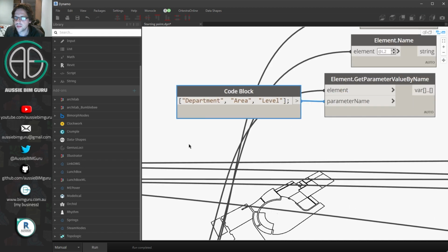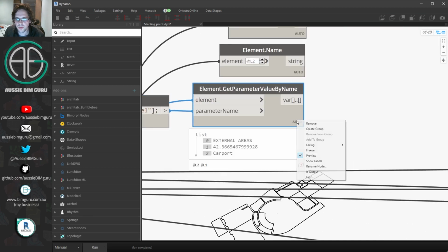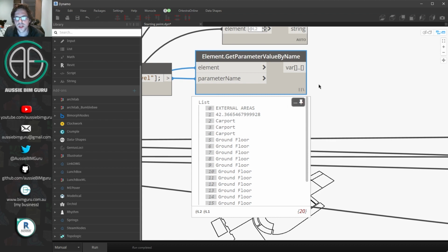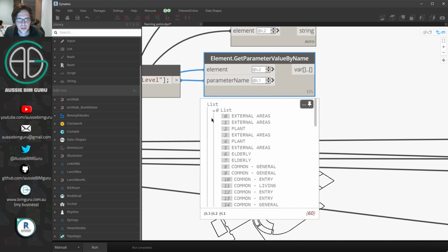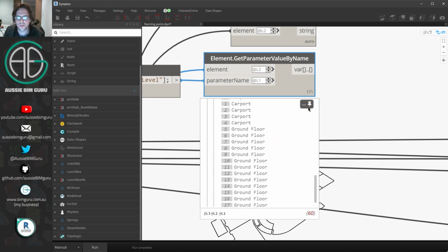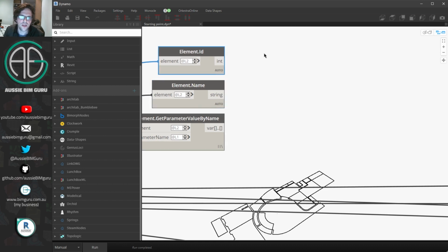It's just a string. So if I work at the standard lacing for this, it won't really give me what I want. If I work at longest lacing, I'll get something that looks a little bit like this. So it's still not really what I want. What I need to do here is say, for this list of elements, I want to search for every single parameter of each of those elements in the list. Now I'll get 3 lists, 1 for each parameter across each room. Because I've worked with these at very particular levels, I can now apply these similarly in a different way.